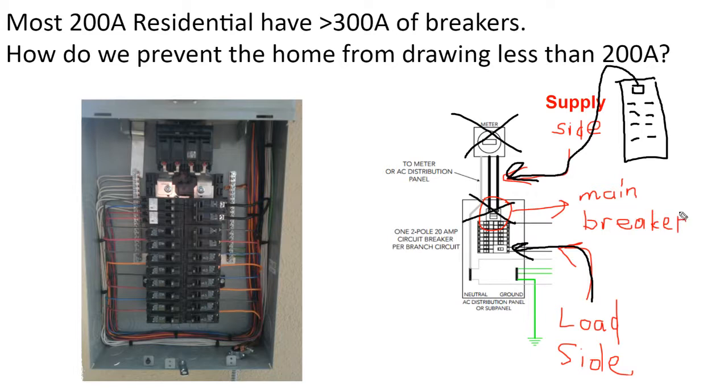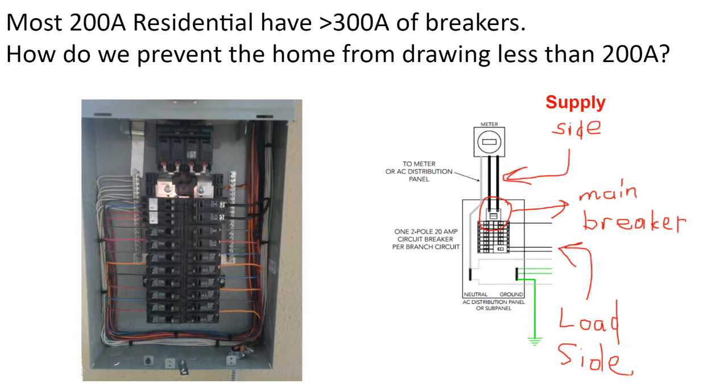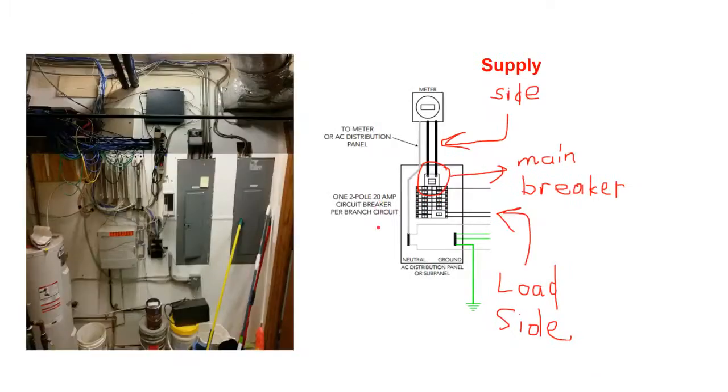But even for small interconnections, supply side connections can be made. Sometimes the inside of the building's electrical system, quite frankly, can be a mess. A supply side connection made outside the building, where the electricity leaves the meter and enters the building, can keep the system inspection outside the building.